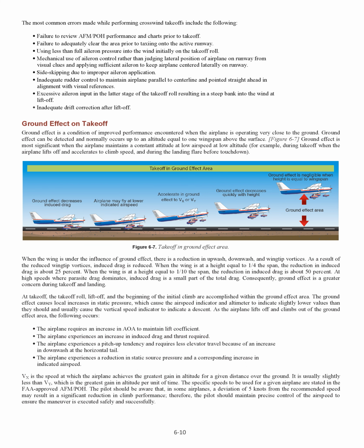Due to the reduced drag and ground effect, the airplane may seem to be able to take off below the recommended airspeed. However, as the airplane climbs out of ground effect below the recommended climb speed, initial climb performance will be much less than at Vy or even Vx. Under conditions of high density altitude, high temperature, and/or maximum gross weight, the airplane may be able to lift off but will be unable to climb out of ground effect.